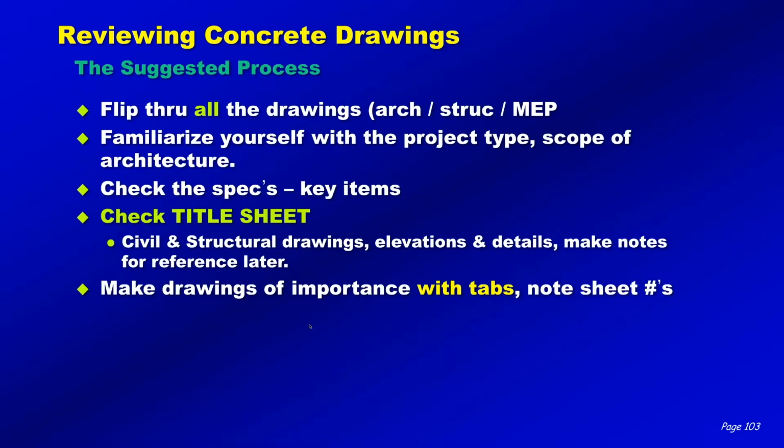So going back to reviewing a concrete set of drawings, what's the first thing I suggested doing? Well, flip through all the drawings and try to get that visualization into your head. Check the specs for your key items. When I work with young students or young people getting into the business, I would throw down a 3-inch set of specifications and tell them, you've got the next 2 days to familiarize yourself with this. I don't mean read every word, but flip through every page and skim those specifications, beginning to get an idea what's in there.